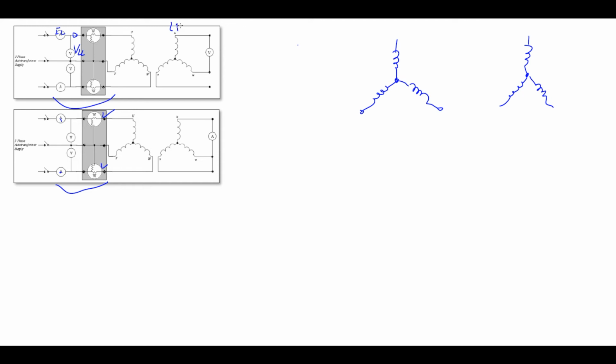In the low voltage side, for both configurations, in open circuit, we can just leave this secondary part open, or we can just connect a voltmeter between two lines to measure the secondary side voltage. For the short circuit, we can make the short circuit using a meter, and a short circuit making wire on the rest of the secondary side.